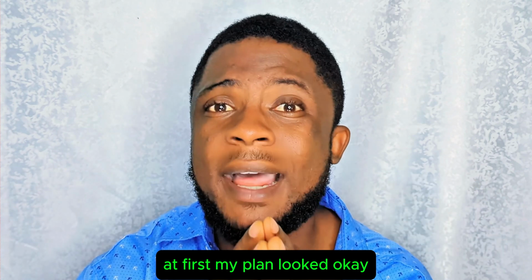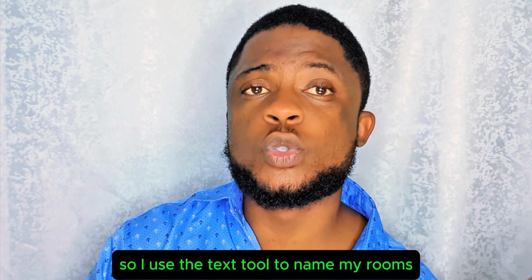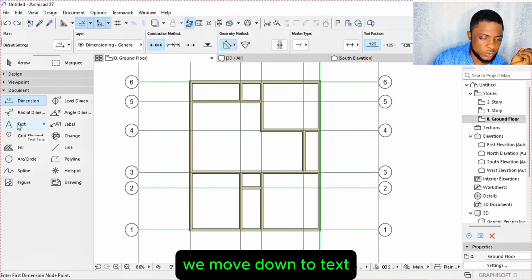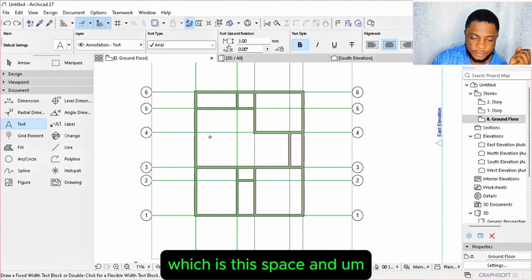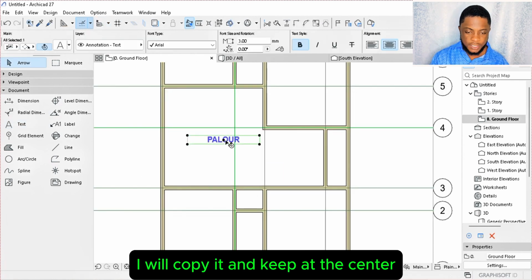At first, my plan looked okay, but I didn't know which room was which. So I used the text tool to name my rooms. And to do that, we navigate to documents, we move down to text, which is written A here, and we click on it. Then we're just going to navigate to our drawing board, which is this space, and create a space where we are going to type in. So I'm going to type in parlor. I will copy it and keep it at the center.